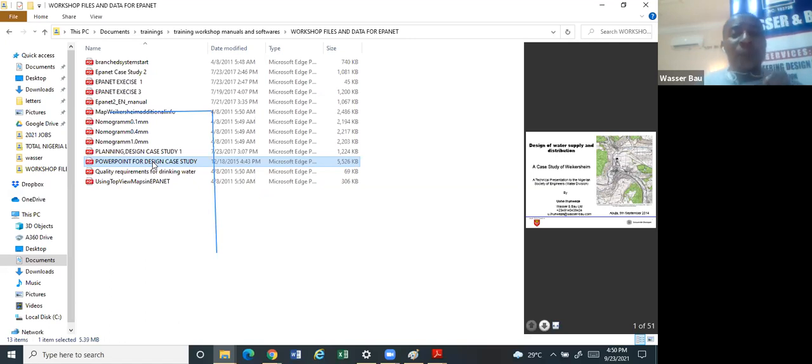Why this is important for us is that most times how to do a design is always the same thing: your introduction, the site analysis, the catchment characterization. You talk about your demand, you estimate your demand, then you generate your factors, and then it's just a simple step-by-step approach, which every design engineer is already used to.